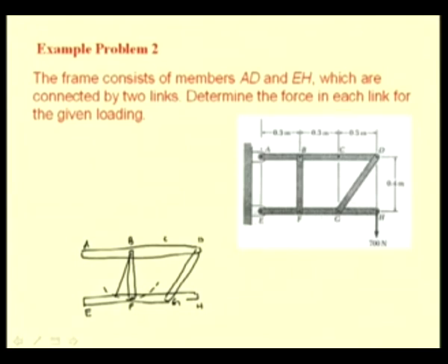In the same way, we also have another two force member, that is DG, which is also rigid. So, any movement is possible such that the point G traces a circular path with radius DG. So, if at all any movement is possible, it is only possible if F traces this path and G traces this path.